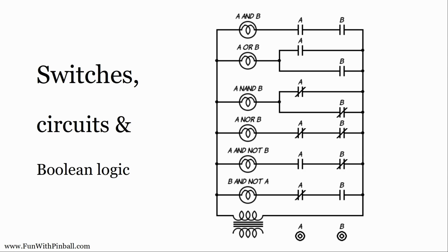Well, reading a schematic is kind of the same way when you're troubleshooting, right? I've identified something that's misbehaving. I think I've identified the coil or the relay that makes that misbehave. So I'm just looking at what circuit, what are the 3 or 4 switches that make that device fire? And I'm looking at a circuit that looks like any one of these lines, right? Start there. And the rest of it you can ignore for the short term, right? You don't have to be intimidated by the whole newspaper schematic.